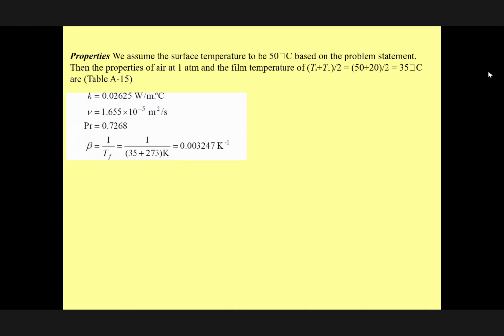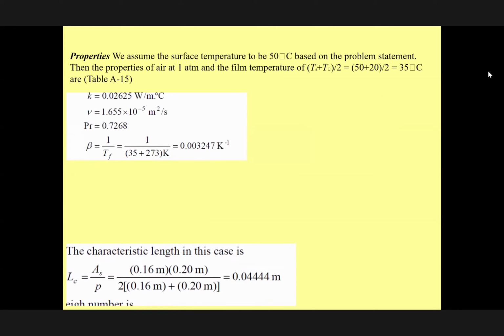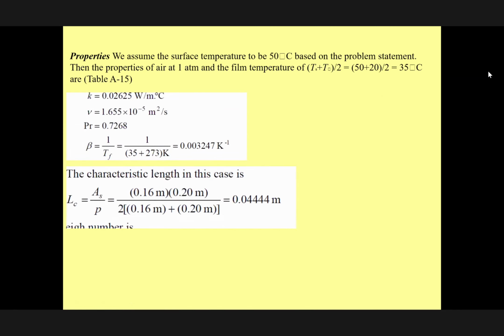Now, again, this is the horizontal plate. When you have a Grashof number, there is a characteristic length, LC. And as mentioned before, LC is equal to area divided by perimeter, okay? This one and this one, both of them, because there is no insulation, okay? So the characteristic length is equal to this one, okay? We have the plate, therefore we can calculate this perimeter and surface area.